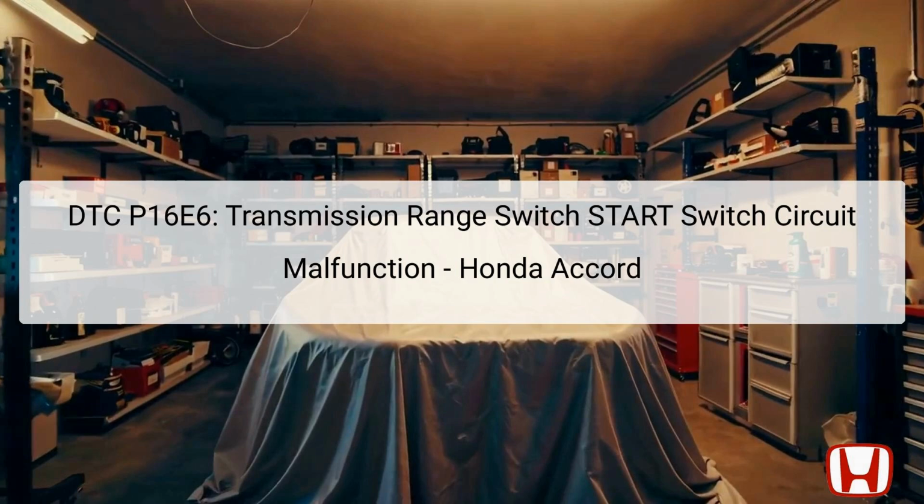The transmission range switch directly impacts the engine control module's ability to recognize the gear position of the transmission, essentially telling the vehicle whether it is safe to start. This switch is generally located on the transmission assembly and ensures that the vehicle only starts in the park, P, or neutral, N, modes.